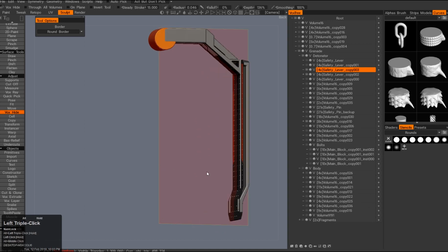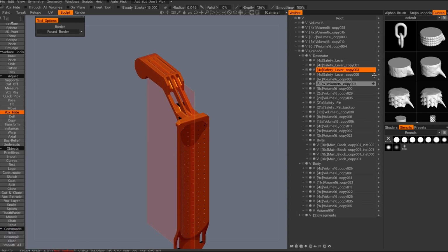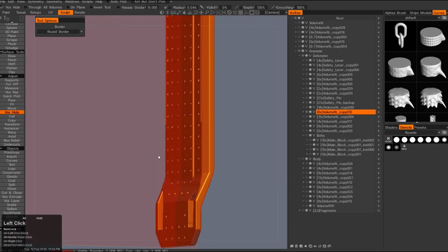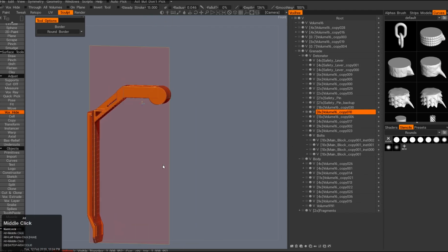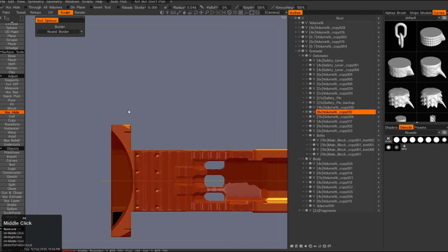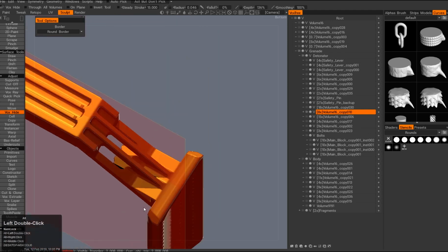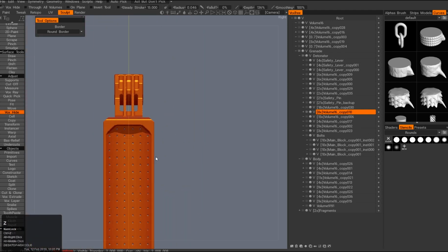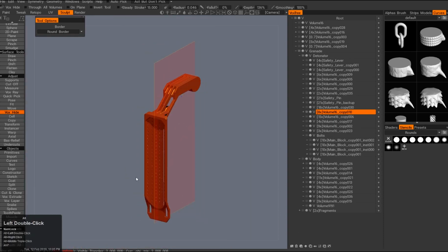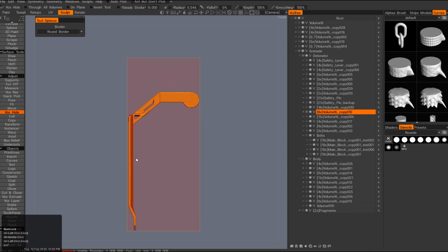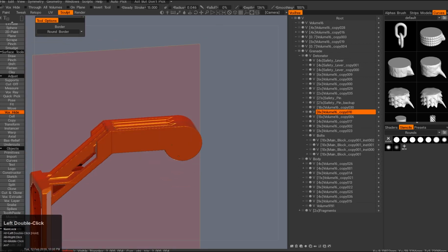I think I had some type of artifact that I'm trying to fix using the older backup copy. Maybe a hole in the spoon on the back, because that mesh is pretty thin right now. And you can see how thin it is at the bottom. So if I smooth this whole part a few times, it's actually going to start creating holes after the smoothing operation. So I wasn't able to run any kind of smoothing on this whole spoon because that would have essentially ruined the mesh.